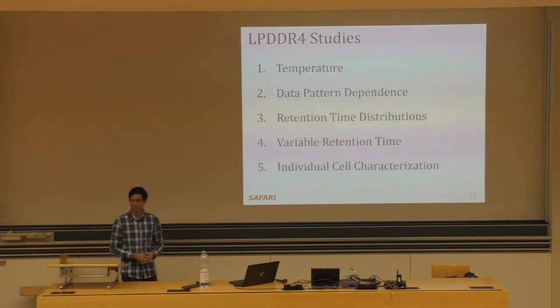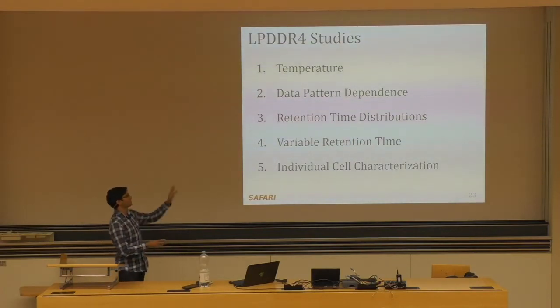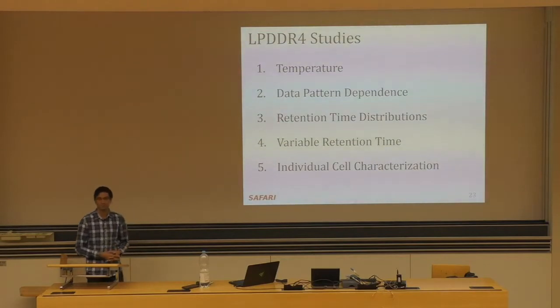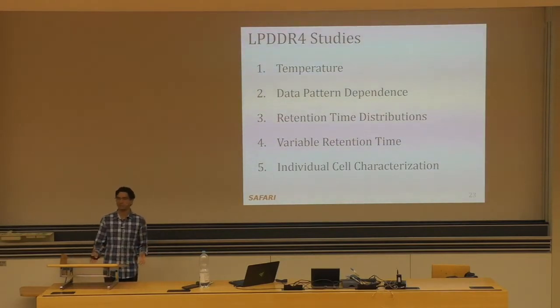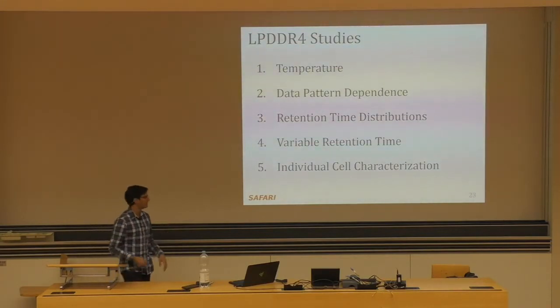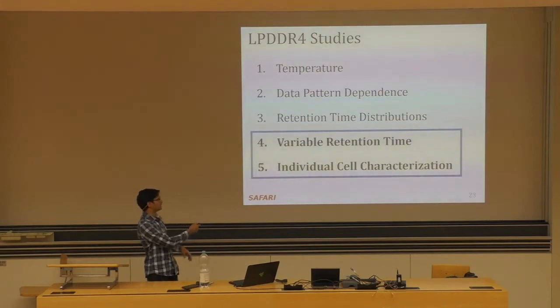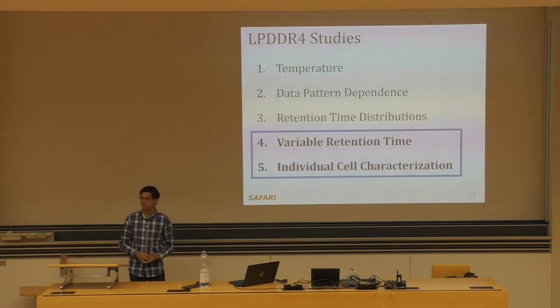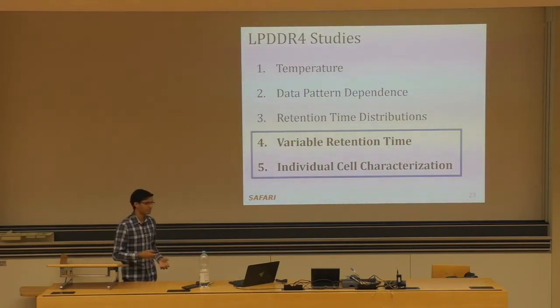And we actually found that the first 3 studies on this list, the temperature, data pattern dependence, and retention time distributions, showed results that were very similar to prior work with older generation devices, so DDR3 devices and so forth. And so I'm not going to focus on them in this talk. Instead, I'm going to focus on the bottom 2, variable retention time and individual cell characterization, because these show new results that help motivate our profiling mechanism.